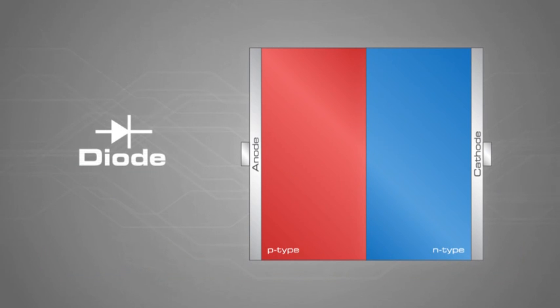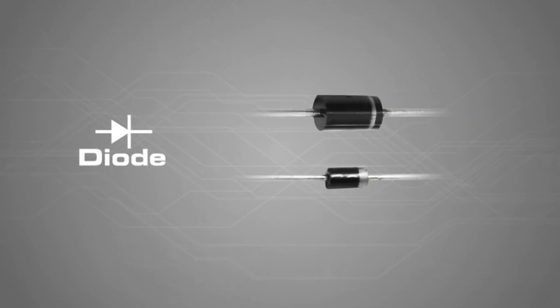A diode is a semiconductor component that has two leads, an anode and a cathode. The anode is the p-type material and the cathode is the n-type material. When drawing a diode in a schematic, the anode is the arrow side of the symbol and the cathode is the side with the line. The diodes that you see in the lab may vary to some degree. However, most diodes are black with a white band on one end indicating the cathode of the diode.